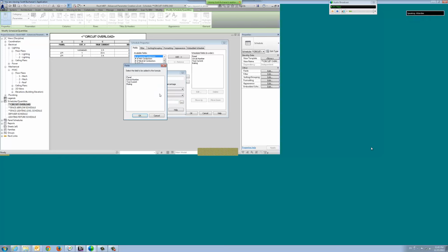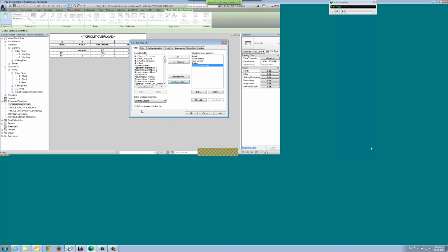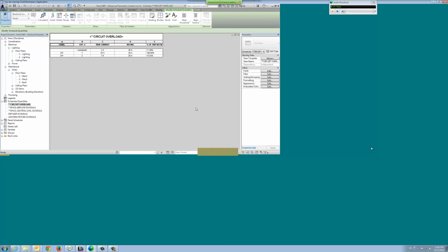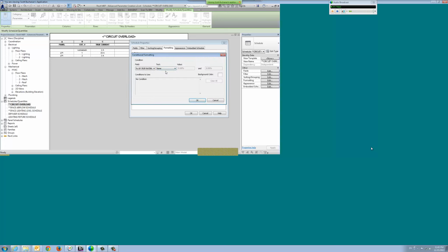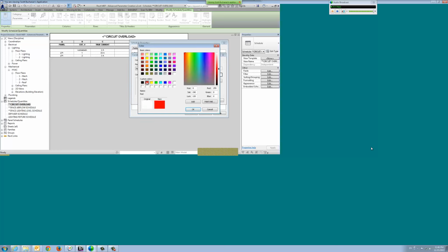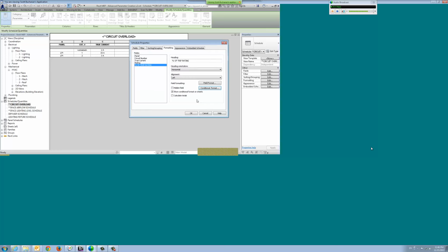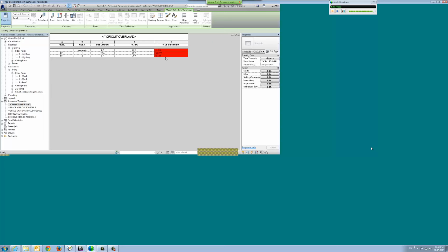Now this formula, again, another straightforward one. So I come in, true current divided by my rating. Go ahead and accept it. And we can see where we fall with that rating. Now, another thing I like to do here, since we want to emphasize this percent of rating, is apply a conditional format to it that just says, hey, if it's greater than 0, flag it red. Again, because I'm just saying, hey, this is the cell I want you to focus on. This is the intent of the schedule, to come in and validate this information right here.